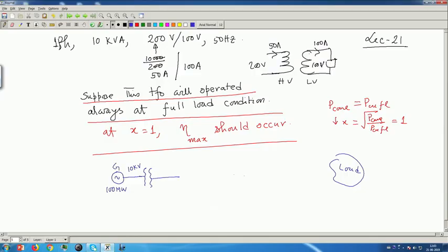I am drawing a single line diagram, and this voltage is stepped up to a very high voltage, maybe 200 kV, or even, in our country we are having 400 kV level voltage. So, here is the transformer who does this. In a transformer, kVA remains the same. So, current on this side will now become less, and then you transmit it.